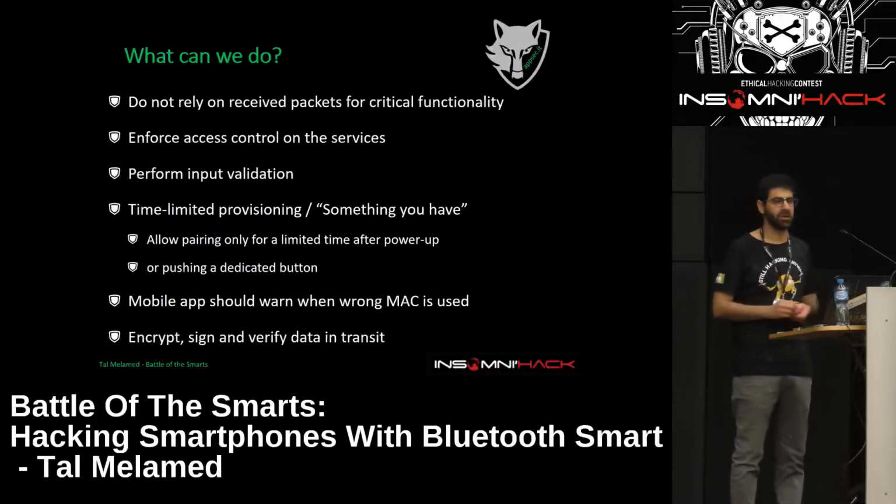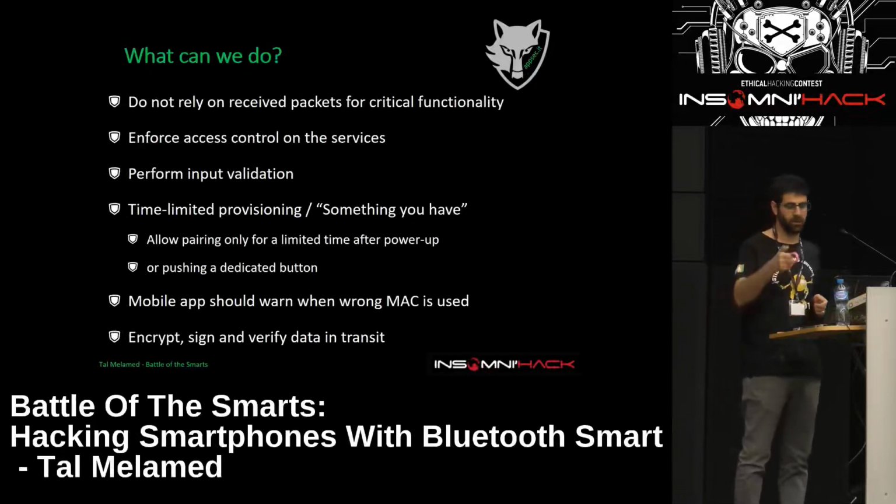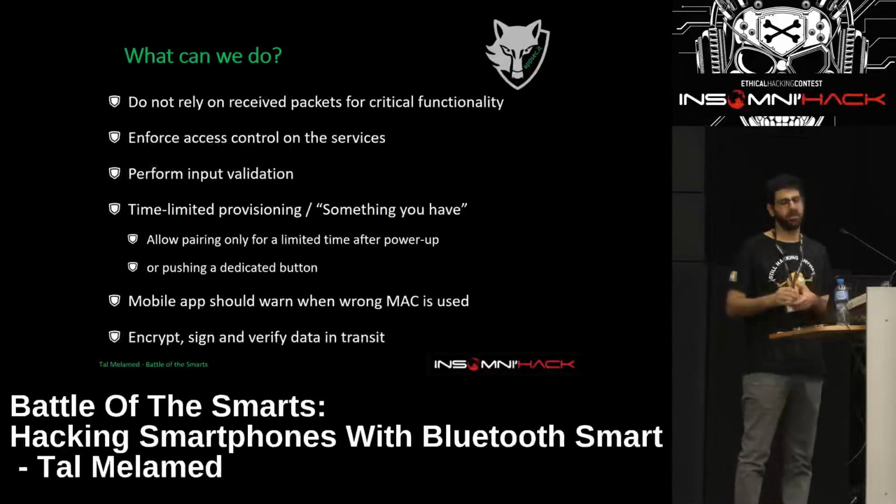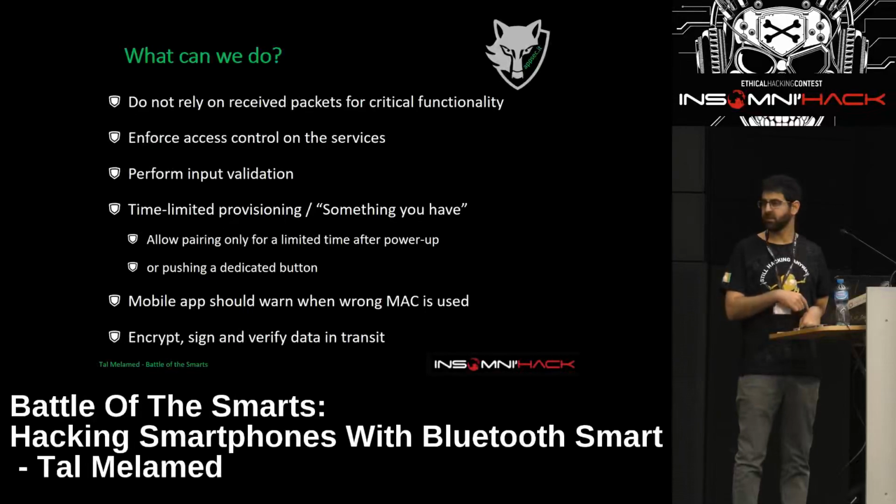We can use a token on the first connection, so the first time we have to click, let's say, on a button, then they bond the pair for the first time, then we store a token, and then without this token or without resetting the device, we cannot further communicate with it. But most importantly, as always, encrypt, sign, verify. These possibilities are provided by the protocol, even 4.0, but they are not used. So do that.